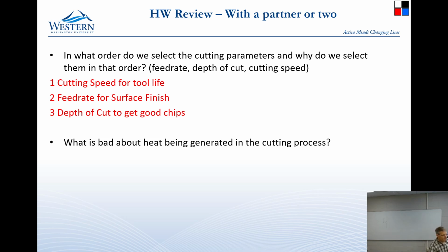You can get crazy warpage in the part. From heat? From thin parts, you know? Not crazy warpage. It can swell. I'm not sure it's from heat. You can swell it a little bit and cut too deep, but most of the warping that happens in a part is from releasing residual stresses that are in it from a previous operation.